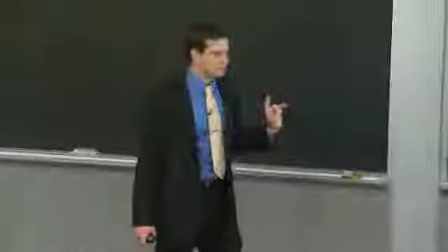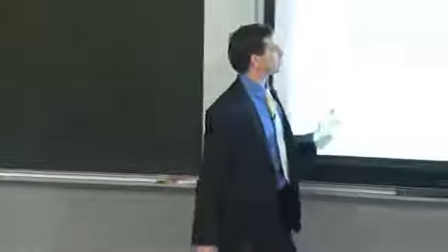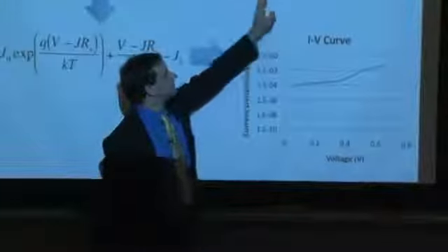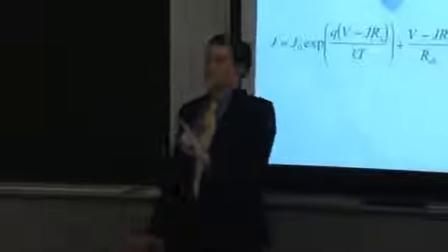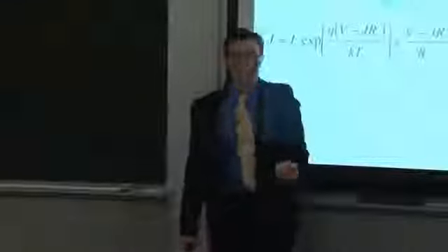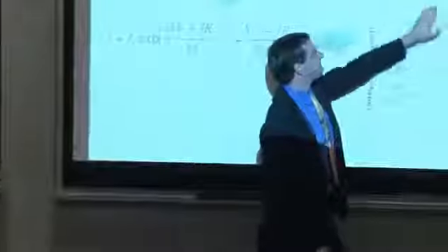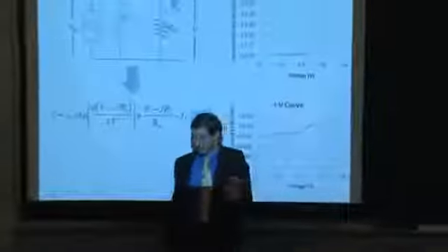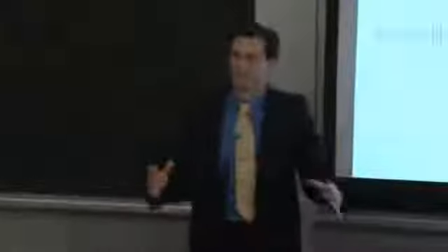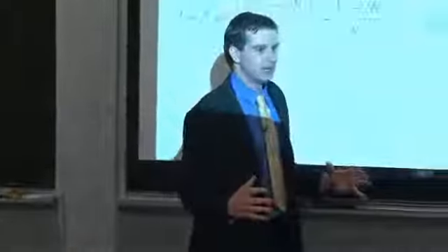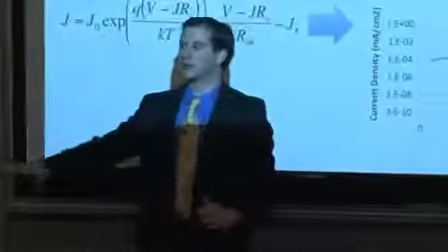So shunt resistance is important for a solar cell device that it not be too high. Sorry, the shunt resistance not be too low. Yes, your shunt resistance can't be too low because at some point it will begin impacting your fill factor. But more importantly, shunt resistance is usually indicative of some localized failure in your p-n junction. It's usually not homogeneously distributed throughout the entire p-n junction.